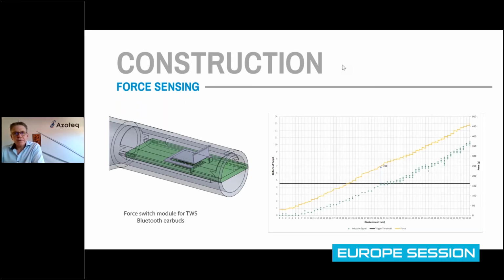Gutierre, if you have a specific example of how fast you want to sample, as well as what precision you require, for something like I have on the screen, for the force sensing, we require a very high precision. So the target counts will be high. It takes longer to take the sample, so inherently higher power consumption when you want very high precision.